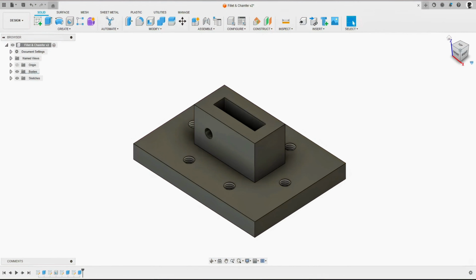In the 2D sketching section of this course, we covered how to add fillets and chamfers to our 2D sketches. And in this lecture, we'll learn how to add these features in 3-dimensional modeling. Adding these features in 3D is our preferred route to adding fillets and chamfers because it avoids any conflicts or losses of dimensions and constraints in sketching, and they are also easy to modify later.